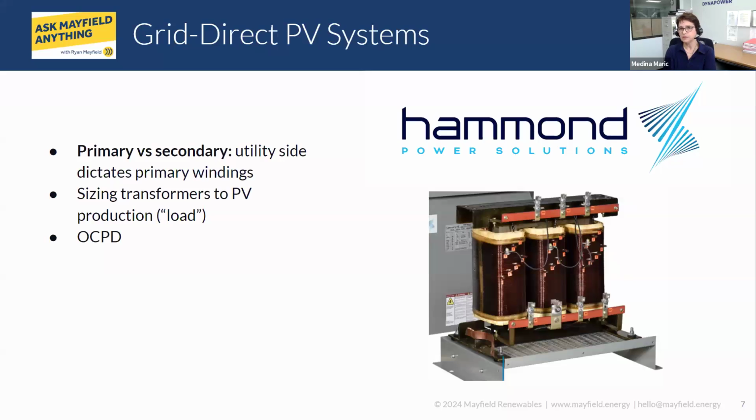Depending on the group and selection of the transformer and complexity, K factor goes very high. With thyristor rectifiers, the minimum K factor will start from 4 and go up. In general, it will be around 13, and there are some ways of mitigating harmonics and making it easier for the transformer, and not throwing those harmonics back into the grid.